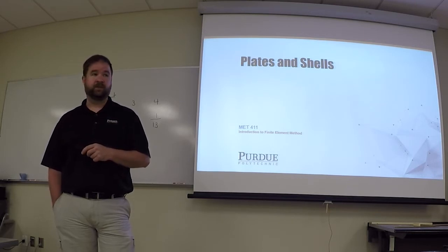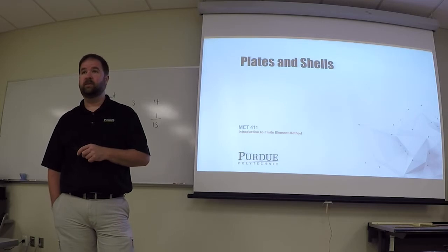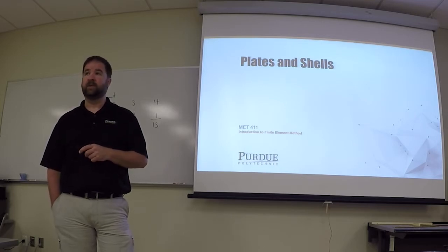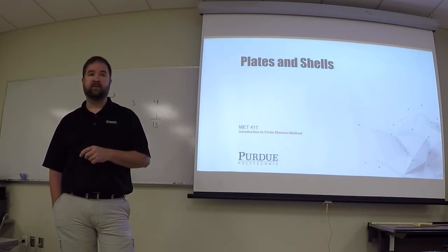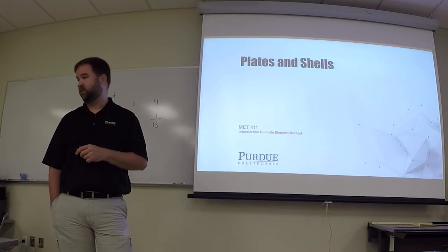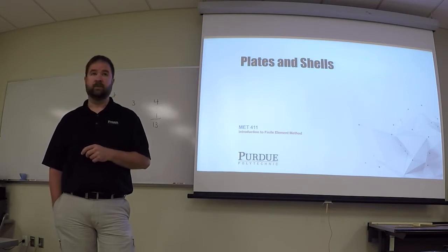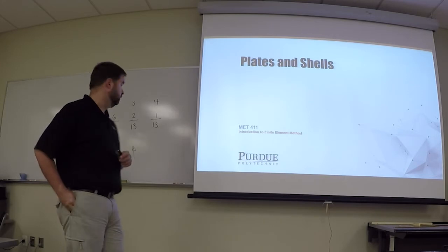So I specifically told you to use the weldment tools, which results in beam elements in SolidWorks. And so you should have finite element models that just look like sticks connected together. Those are 1-dimensional elements.